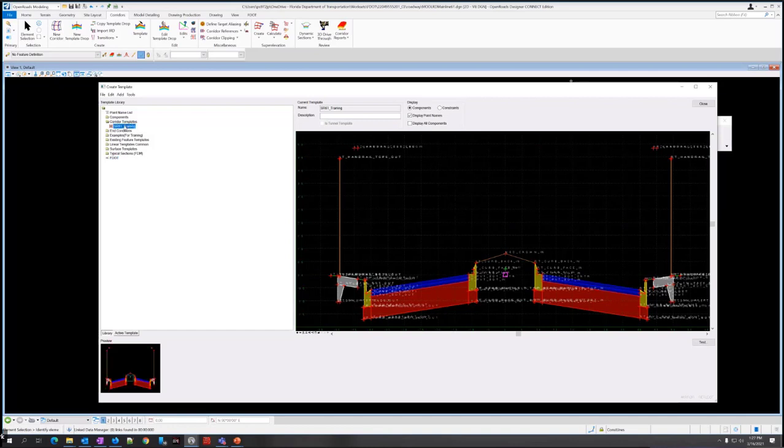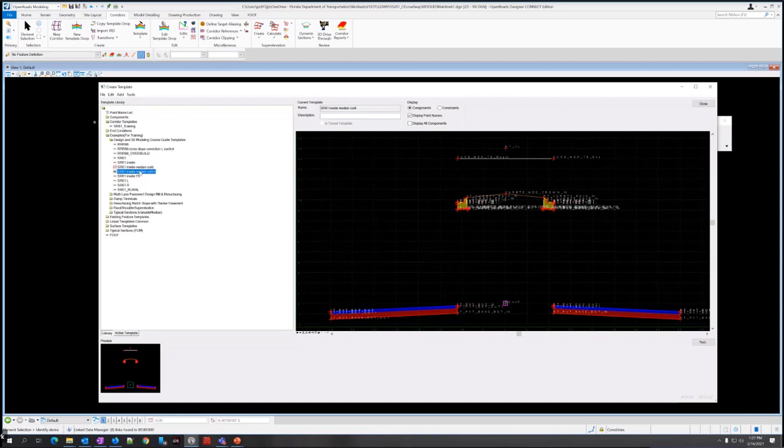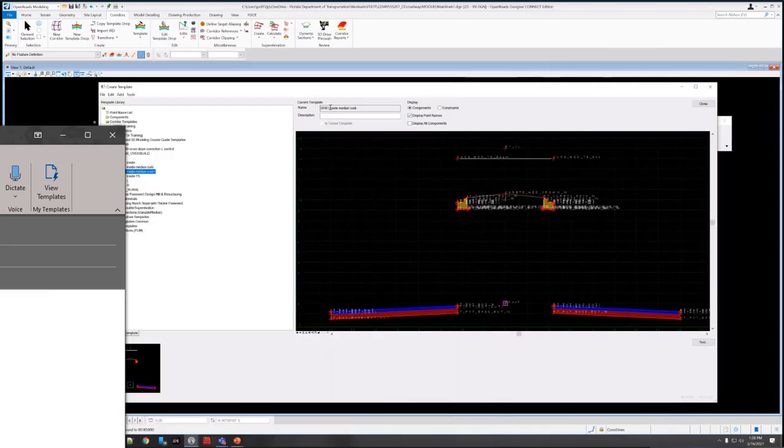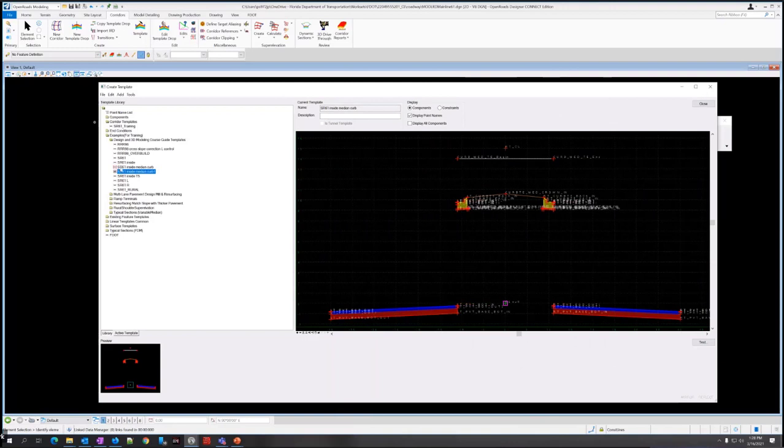The biggest thing is when you're making a copy of one that looks very similar, you can run into trouble with that. For example, if I have a couple similar looking ones like these two. So I have two, curb and curb one. So if I select this one, you just got to be aware which one you're editing. So up here, current template. This is your active one. So even though I may have selected a different one here, you're editing the active template. Make any edits here. So you can check your name up here of the current template. Check for the red box over here, just to make sure you're editing the right template.